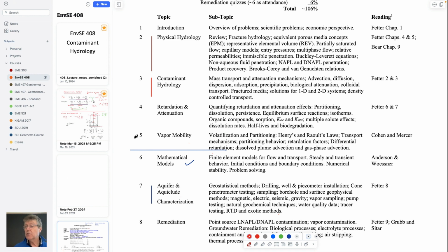You know that they dissolve slowly, and so they're quite persistent, and so if you don't remove the source, then for remediation methods, you don't really solve your problem, but you just deal with the consequences in perpetuity, like pump and treat. We talked about how the concentrations and the rates at which they move downstream might be conditioned by the fact that retardation and attenuation occurs, by sorption onto mainly organic carbon, but also onto the substrate surfaces of the grains that we have as we're going downstream.